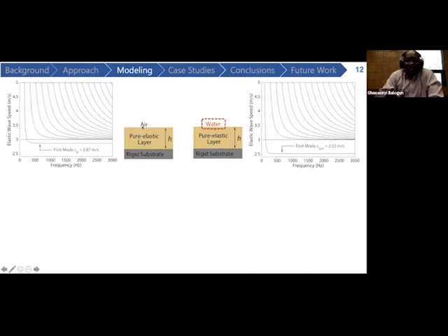So it's no longer a Rayleigh wave, but actually a coupled wave in which the energy of the elastic wave couples into the water and the elastic layer. The other features in the curves are essentially the same. You have the shear wave speed, which is this horizontal constant line, and then the other curves representing the guided waves, the standing wave modes that travel from left to right. Okay, so now let's see what happens when we introduce a viscoelastic layer.